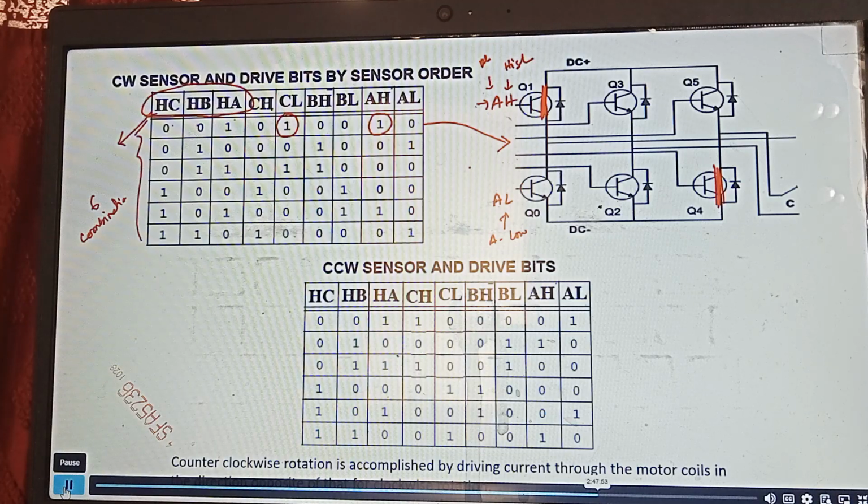So this is how one of the answer that I gave. Hall sensor or any position sensor in the rotor, these are responsible to eventually deciding your switching states, directly or indirectly, okay? So here at any point of time, you can see only 2 devices will be conducting. So 1 means on, 0 means off. This for BLDC, okay?